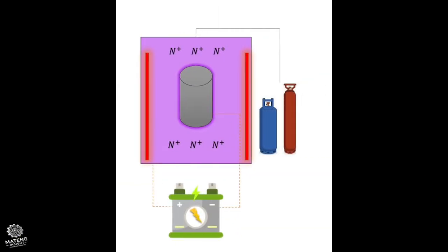In a hot wall furnace, heating elements are embedded into the chamber walls in addition to the plasma. These elements provide a more uniform background temperature, meaning less heating is required from the plasma itself. As a result, process control is more stable and precise, since temperature distribution and nitrogen diffusion can be regulated more effectively, minimizing the risk of hotspots.